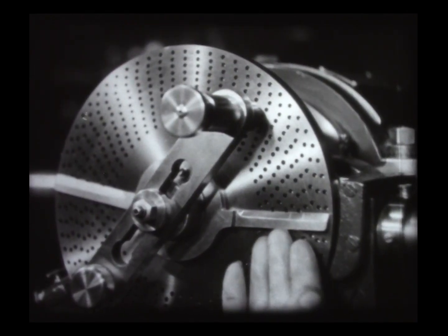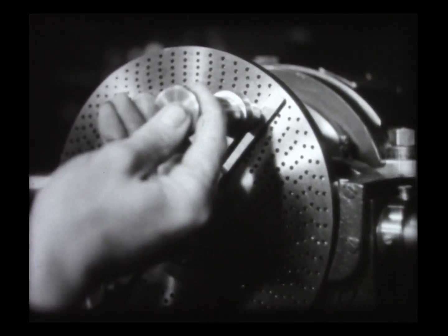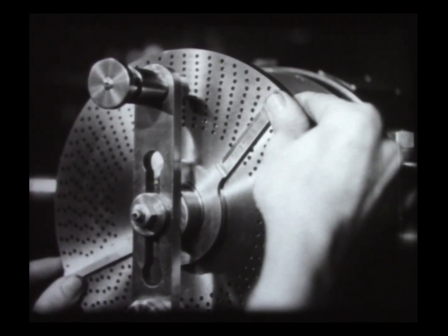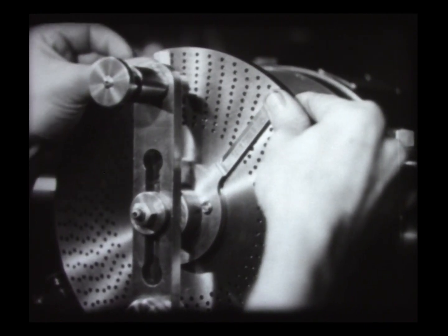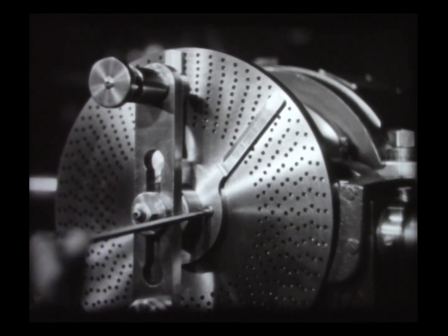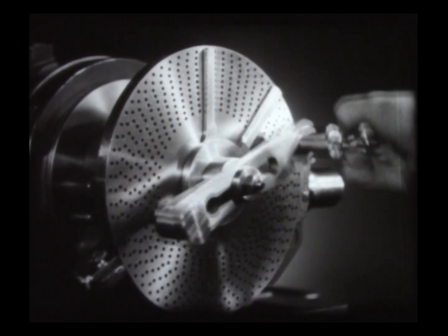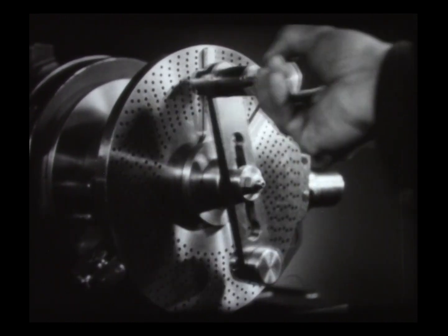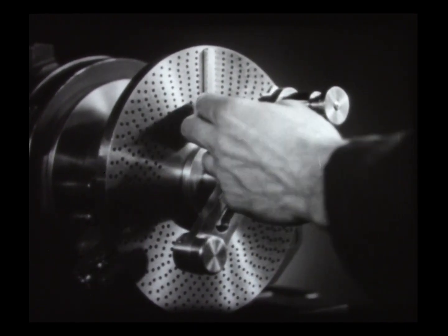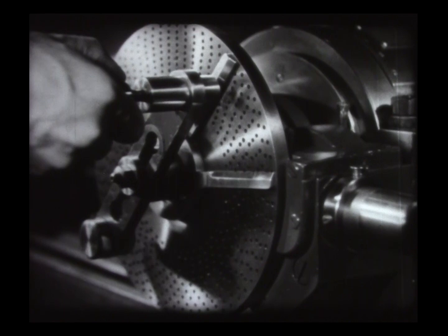To simplify the operation, a sector is used as a gauge. Adjusting the sector to 6 spaces eliminates the necessity of counting out the number of spaces each time a cut is to be located, since the distance between both blades of the sector equals 1/9 of a turn. Moving the sector against the back of the pin automatically locates the starting point for the next 1 1/9 of a turn.